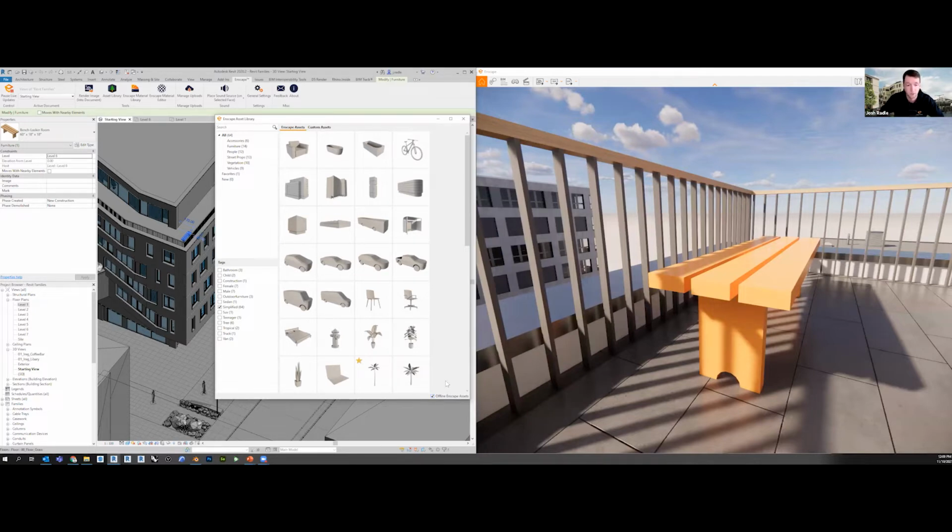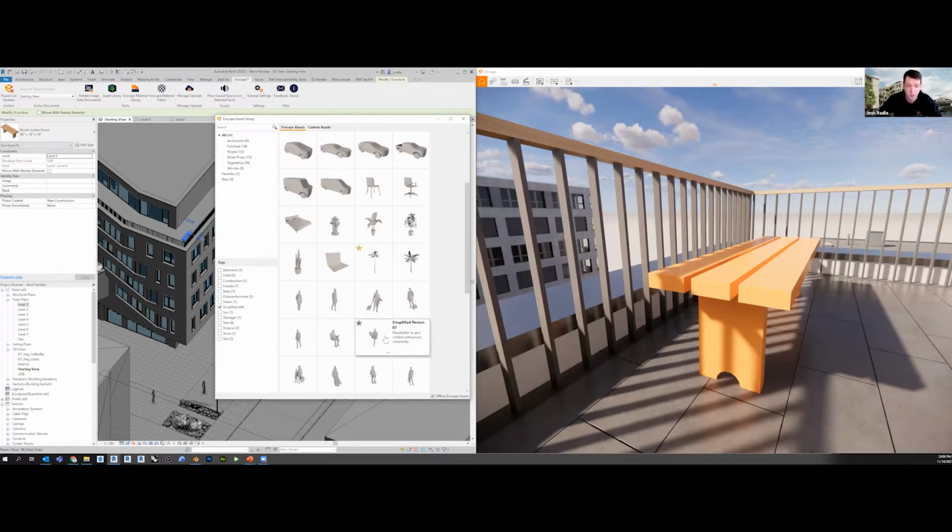If you don't, there's a warning that's going to pop up saying Enscape will remove anything that is in the folder that you've selected. So you can imagine if you set these to be downloaded to your desktop, all 2,500 different Enscape assets are going to be downloaded to your desktop, and whatever's on it is going to be removed. That's why we create a folder first and then point these assets to go into that folder. So that was just a tech tip on how you can get these scrolling a lot faster. But let's start placing some of these.